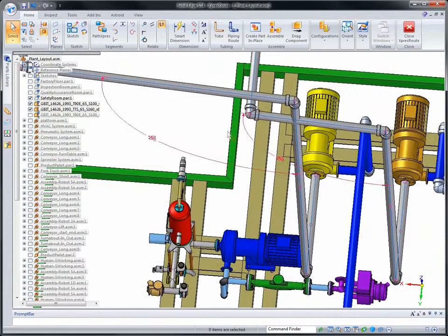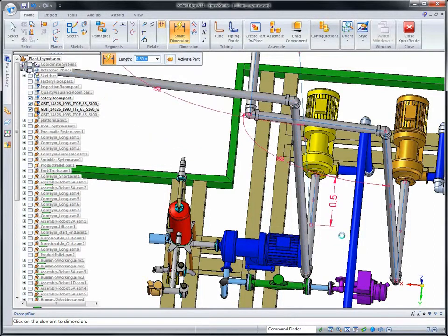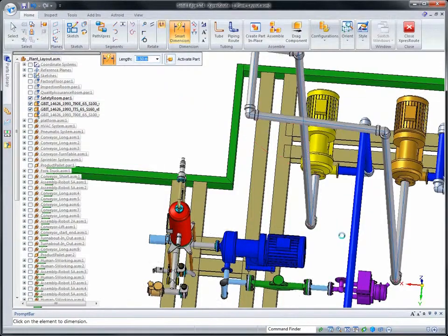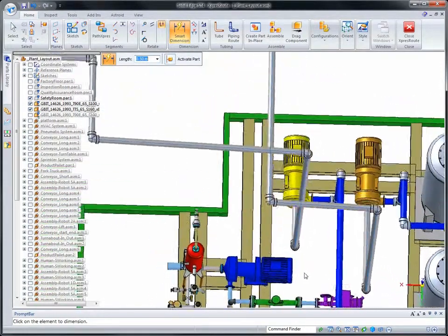And so to fix this, it's quite easy. All we need to do is add a dimension to the path coming from the pump and change that dimension, which is going to adjust the path. And when we do that, just like changing the angle, the pipe's going to automatically update to the change to the path. And this removes our interference.